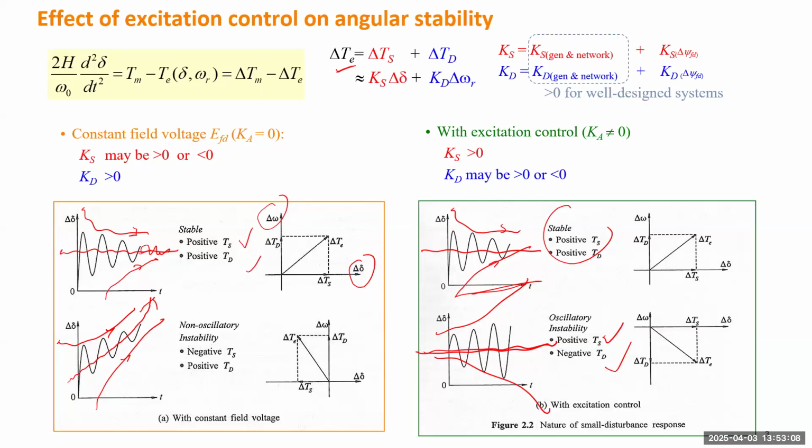The waveform will have smaller amplitude, but if the generator flies away, it causes an out-of-step issue. That's definitely bad. If I use the excitation control to enforce the synchronizing torque, it will stay close to the equilibrium, but the amplitude can be growing.